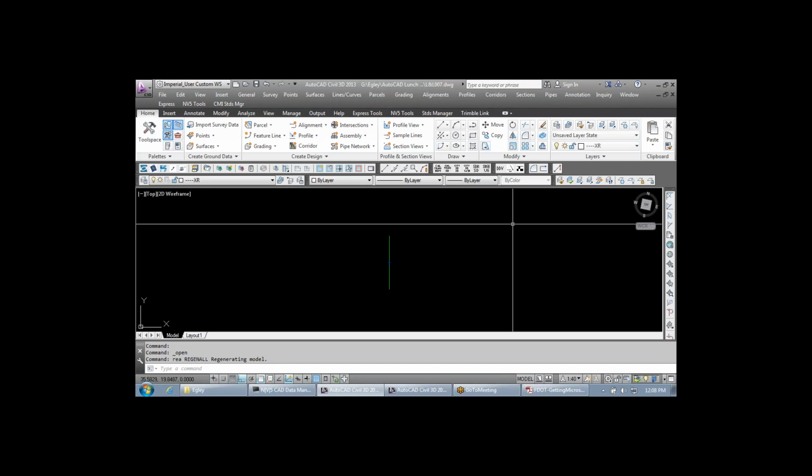We also talked a little bit about what happens when you explode feature lines, specifically when they have an arc as part of your feature line. And we talked a little bit about using a flattened site to help aid in that. We learned a little bit about the offset gap type command. We also learned a shortcut on how to edit attributes within a block. If you hit Control and double click it, it will act like regular text.